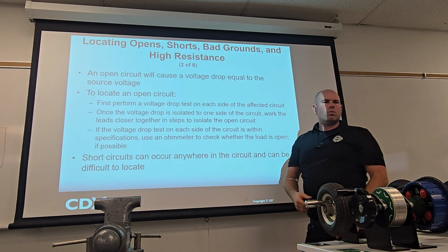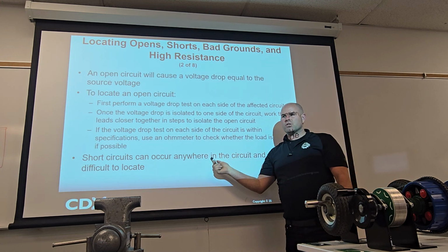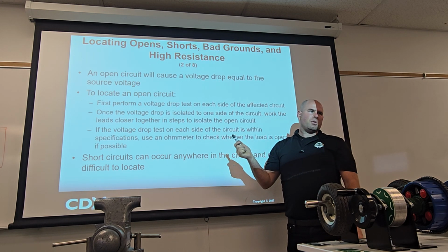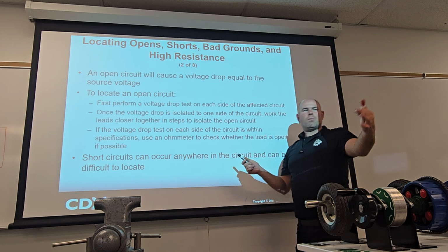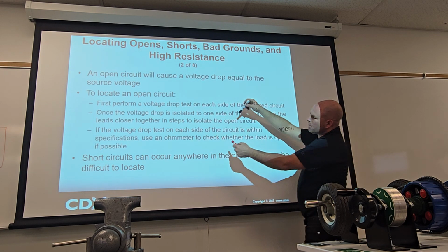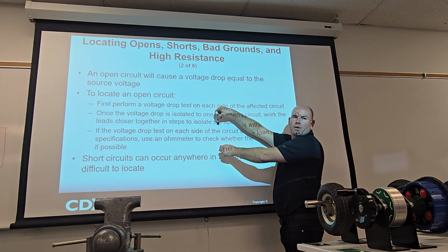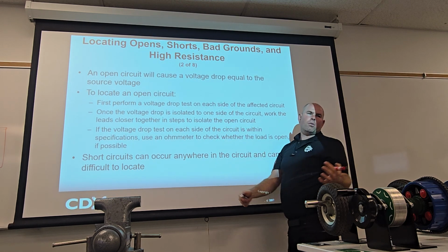Did you know if a bulb was blown, it'll drop 12 volts across the bulb? But is the bulb good or bad? So one more step you could do is put it on ohms and then measure the resistance of the bulb. What should the resistance of the bulb be, would you say?